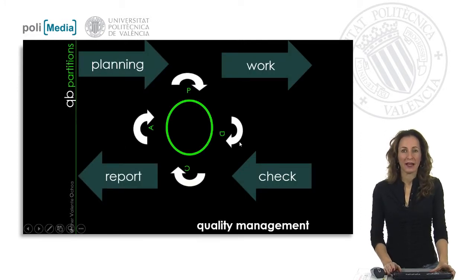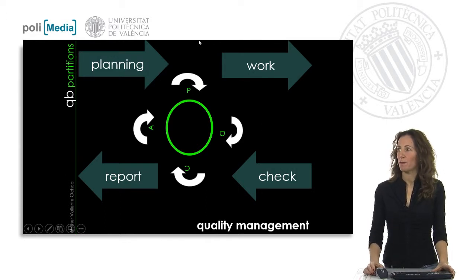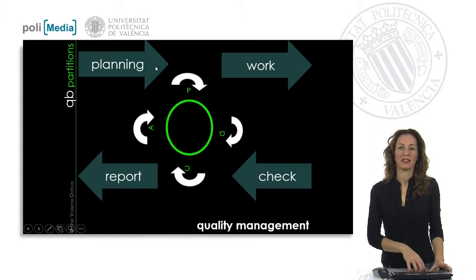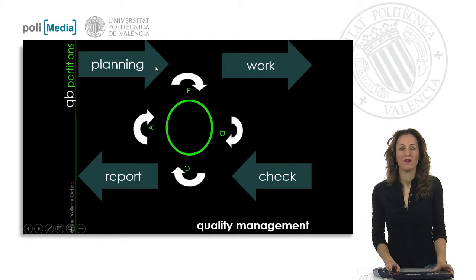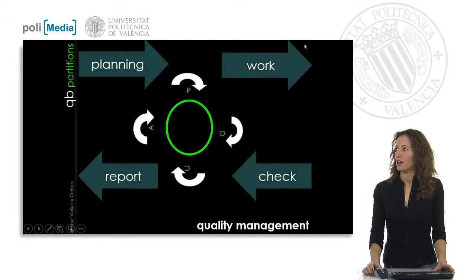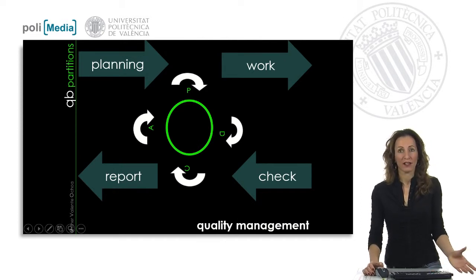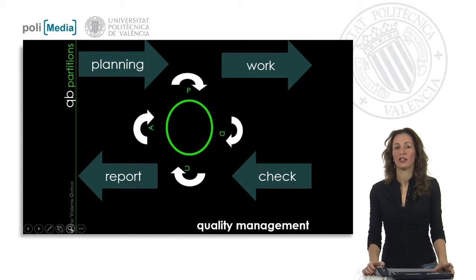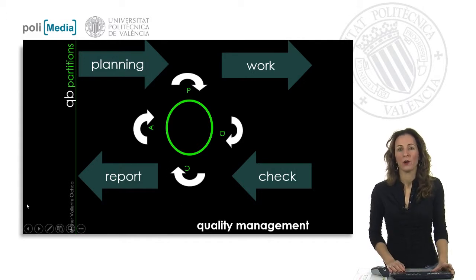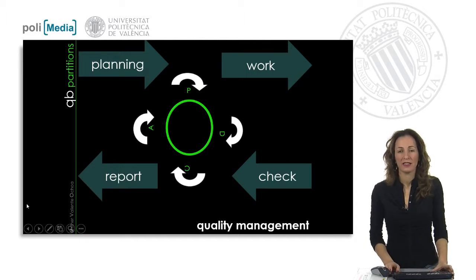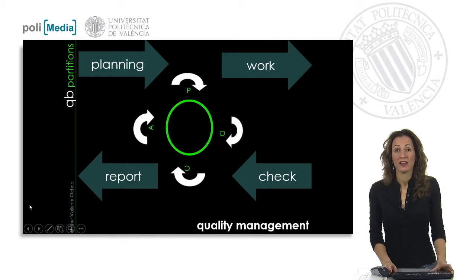First, I would like to remind the Deming circle principles: plan, do, check, act. Start with the planning from the project management, where the mandatory specifications about the materials and the units to execute will be reflected. Also, during the construction works, we have to check all the activities, and in case we find any damage or any failure, we should report the non-conformity report and join this one with a corrective action or a preventive action that will repair this damage and will also prevent the repetition of this in many cases.